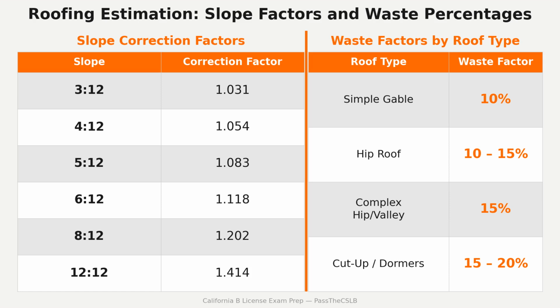Here's the California answer for warning line placement on low-slope commercial roofs: 5 feet from the unprotected edge. California's Title 8 Safety Code, Section 1730, specifies 5 feet. Federal says 6. California says 5. On a California licensing exam, if you write 6 feet for warning line placement, that is the wrong answer. I wanted you to feel that discrepancy. That is how it sticks.